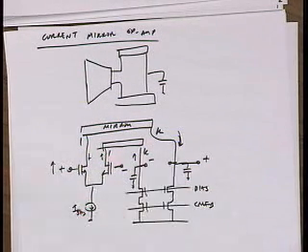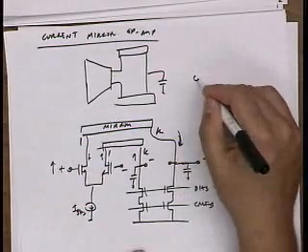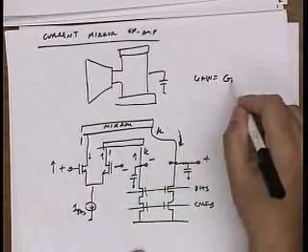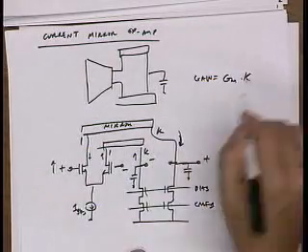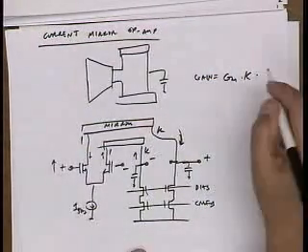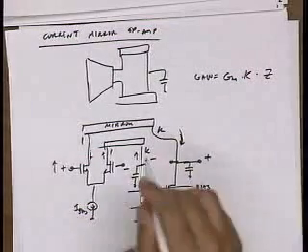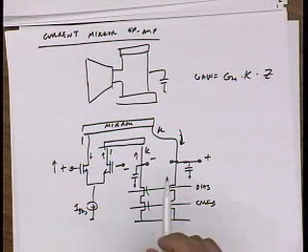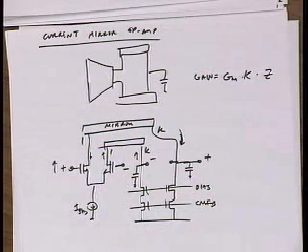We've looked at amplifiers very similar to this. The DC gain is no different than all the others we've seen. You have a GM stage, you have a current gain stage, and then you have the output impedance, the high impedance node here. So again, it looks a lot like what we've studied before. How about the choice of, well, let's talk about the poles. Again, where do we think the non-dominant poles for this circuit are going to come from?